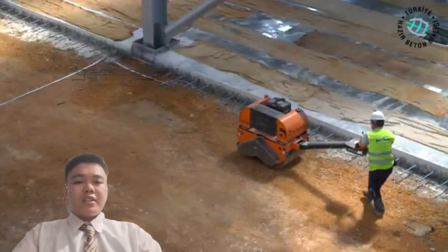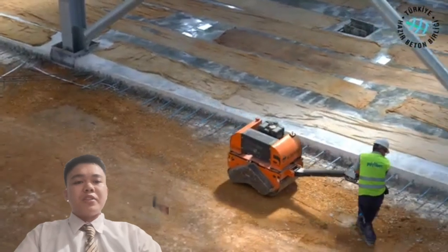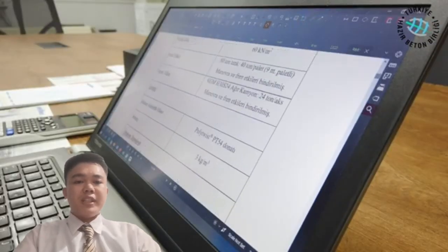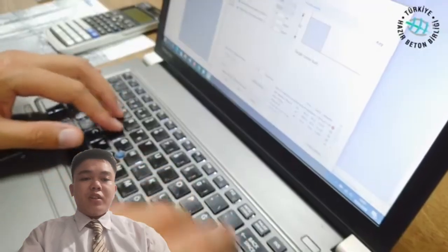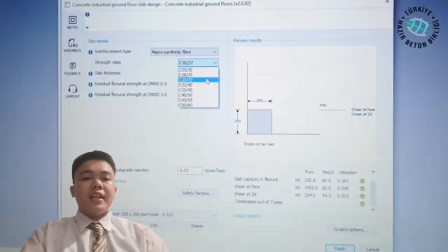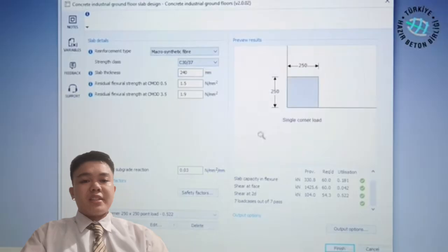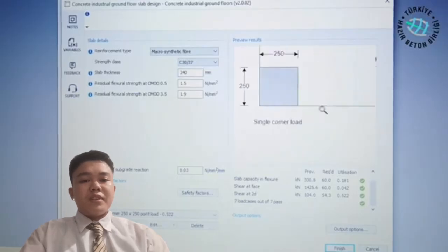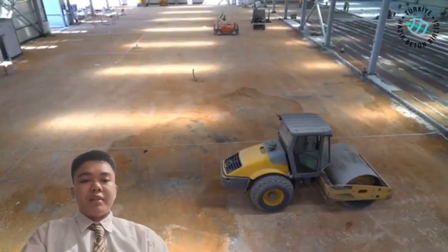Through improved crack resistance, a denser microstructure, and self-healing capabilities, this technology also reduces maintenance costs by up to 50% as bacteria seal cracks before harmful substances can cause further damage.